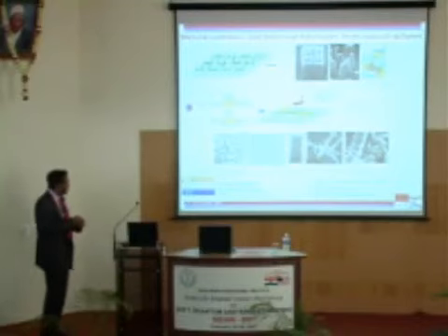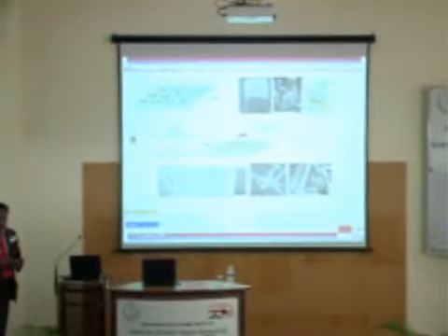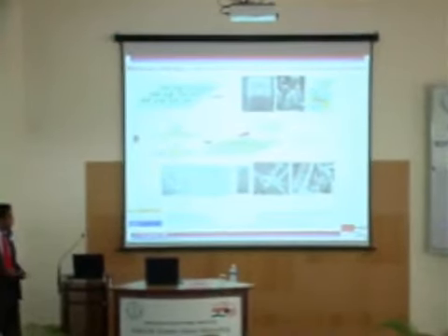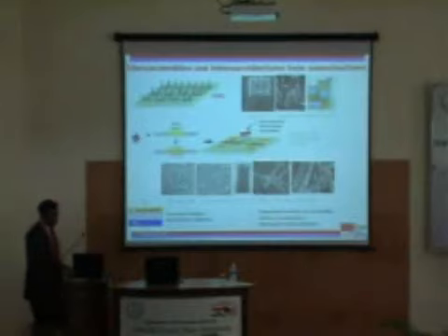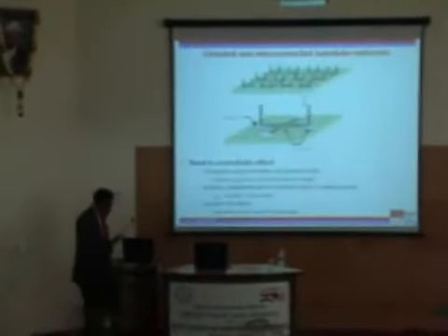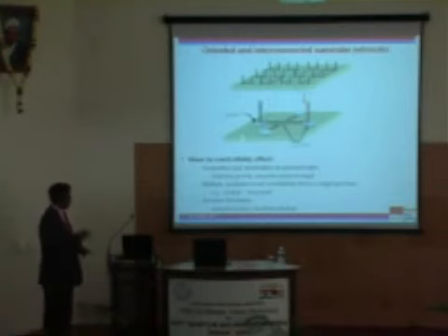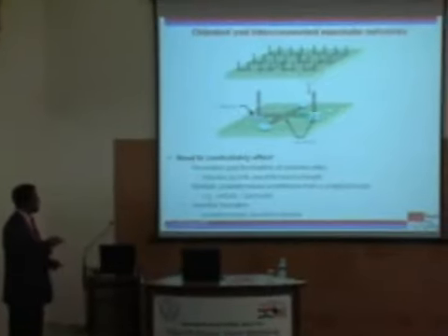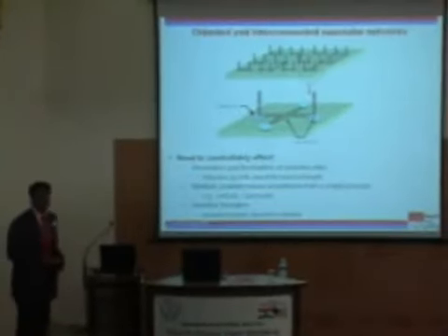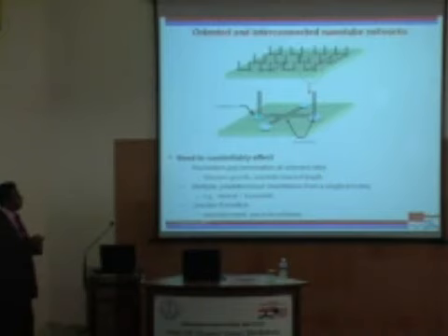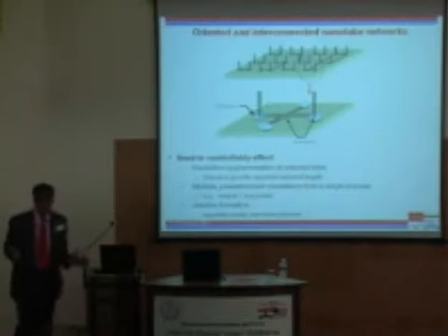So isolating while maintaining the structural integrity of these structures is very important, and I'll talk about that a little bit before I conclude my talk. Okay, let's talk about carbon nanotubes. Let's just say that these are one-dimensional, wire-like molecular structures which have very nice electrical properties. Okay, and you can have ballistic electron transport, and depending upon the actual crystal structure or the chirality of the tubes, they can be semiconducting or metallic, and you can think about various different kinds of quantum devices you can make.